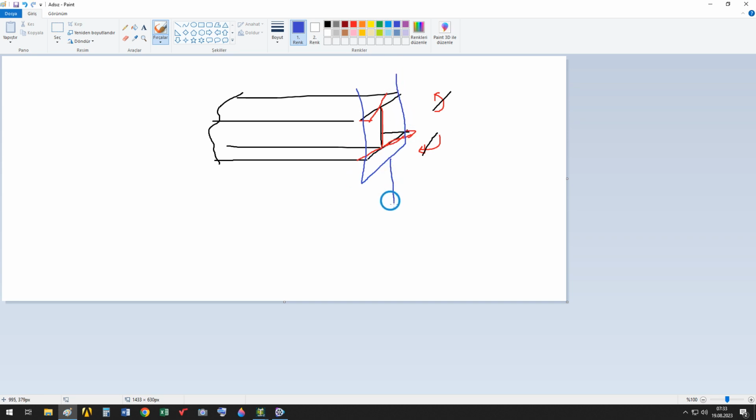The top and bottom flanges can make those deflections, because in the plane of the top and bottom flanges, no restraint by any wall or similar can be applied to the top and bottom flanges of the beam or member.